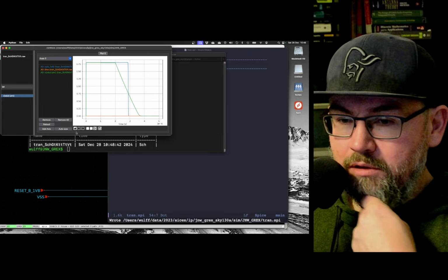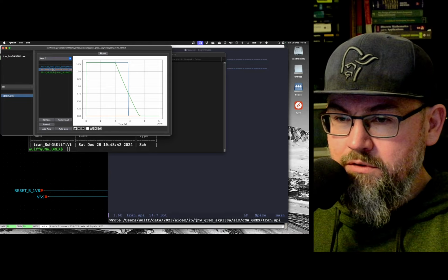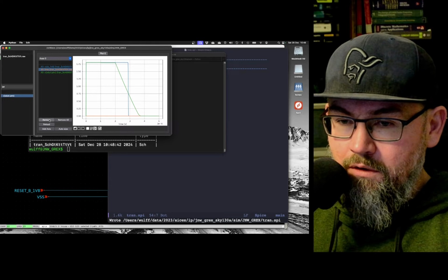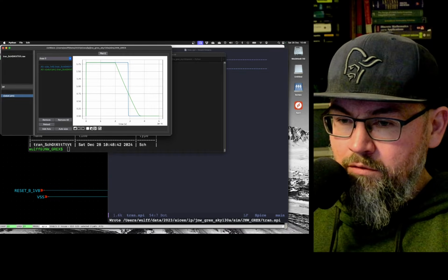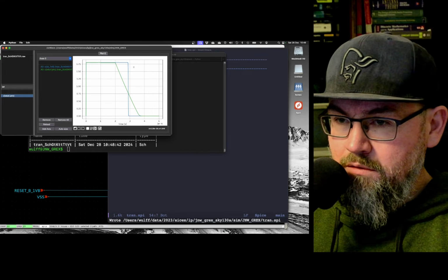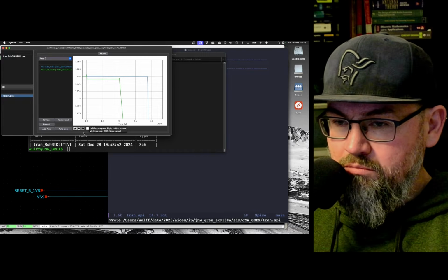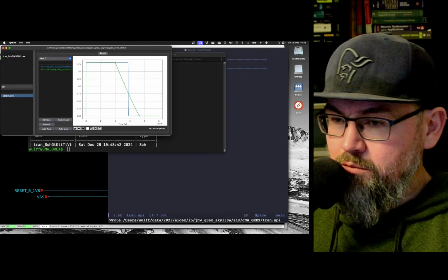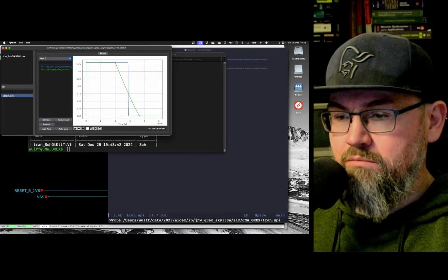Okay, let's have a look here. So what happens? Time we can delete. When we turn on the reset, there's a small charge injection on the cap. Let's ignore that for now. And then we see a pretty linear curve until it gets down here and it flips.